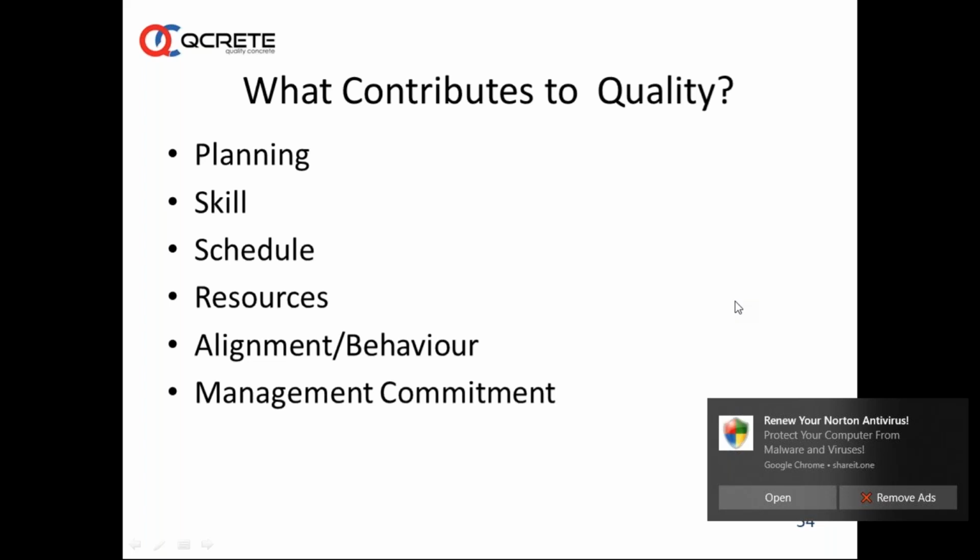Sometimes we find 7-day strength achieved but 28 days strength remains the same. Mr. Siddharth Shah is asking this question actually. Many times what happens is, let us say somebody has cast a set of 3 cubes. The generally acceptable or expected variation within the set of 3 cubes is about 2 to 3 MPa, 1.5 MPa, 2 MPa. If everything goes well, there will be a variation of 2 to 3 MPa between cube to cube in a set of 3 cubes.